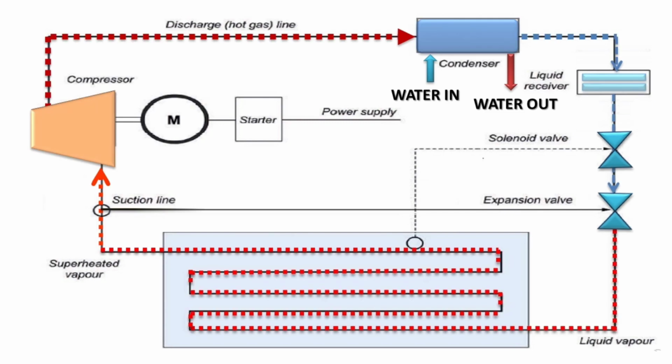The refrigerant fluid is passed through the compressor. The compressor's job is to raise the pressure of the vaporized refrigerant. This high pressure helps pump the refrigerant fluid around the system. While the pressure increases, the temperature of the refrigerant also increases. Now the refrigerant is in a state of superheat, a high pressure vapor with a temperature of 90 degrees Celsius and a pressure of 11.92 bar.